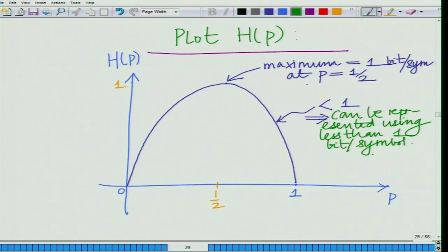And this is what the encoding process does, right? The encoding process is expected to take these source symbols and come up with an efficient code, an efficient information bit stream, to represent this using the minimum number of bits. Take two binary symbols S0 and S1, and come up with an information bit stream to represent this efficiently using the least number of possible bits, that is the lowest possible bits in an average sense, that is, the average number of bits used to represent each symbol must be the smallest. Okay, and this process is termed coding or encoding.